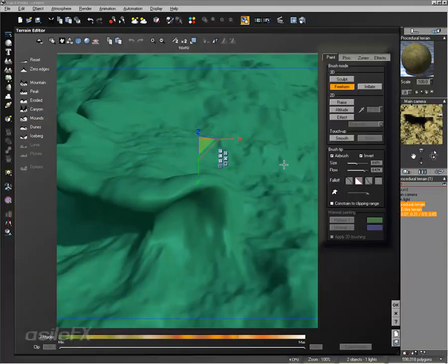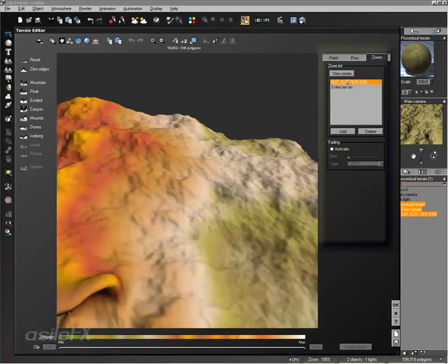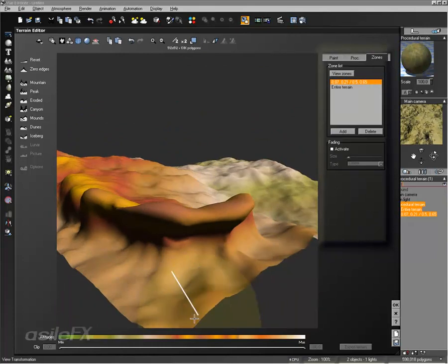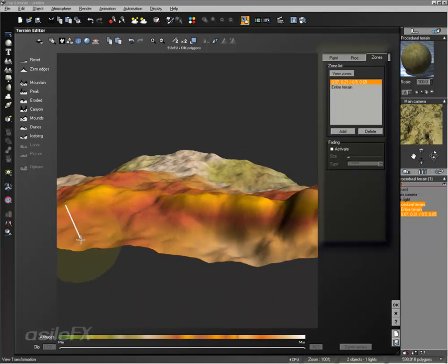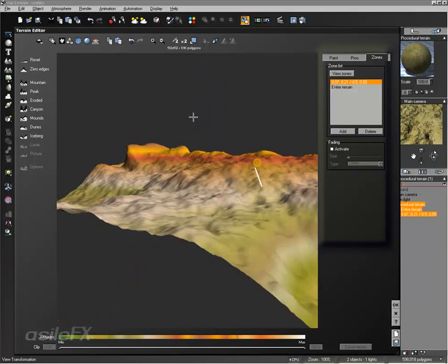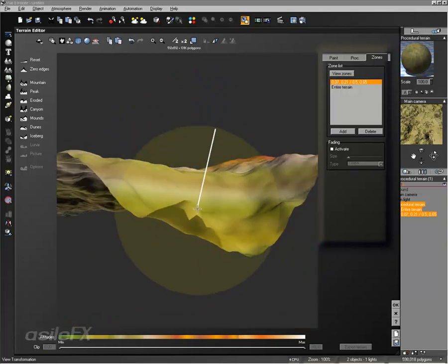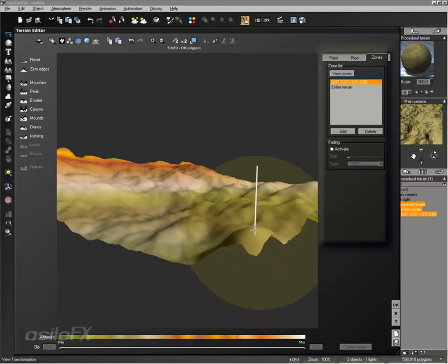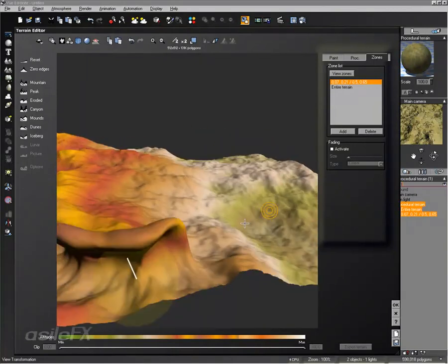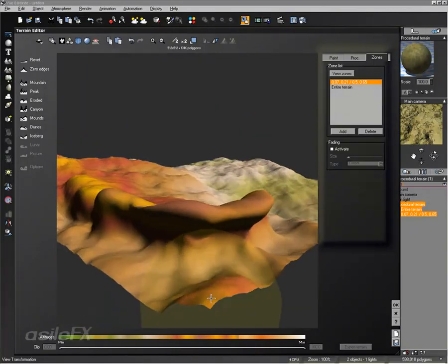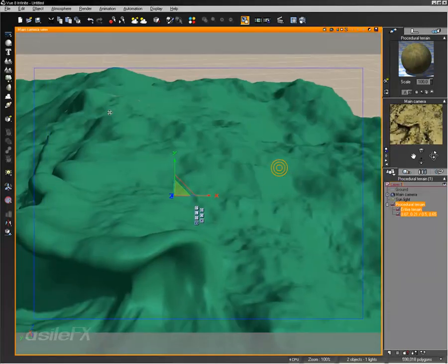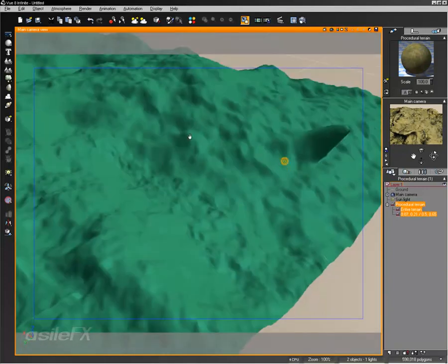But let's go ahead and make some modifications to kind of force that to happen. Go into the zone, and what I'm going to do is modify the edge. And we're going to be able to see a little bit better. What I'm also going to do is just, for the purpose of previewing, to show you, I'm going to pull up the corners so that we can also see a preview of the zone a little easier within the interface. Not suggested, however, if you're going to actually be working on a project. So this is just to preview it for right now. And that way we can see the corners lifted for the edges of the zone.